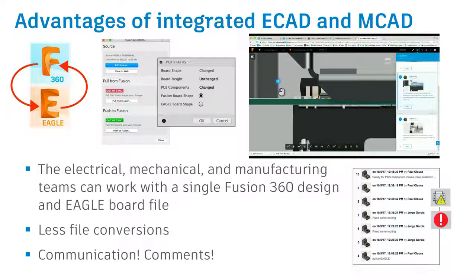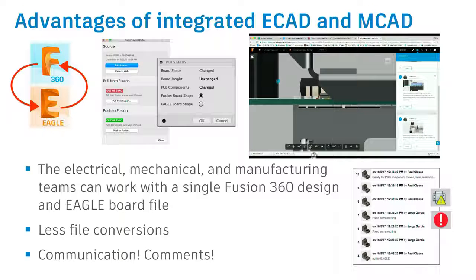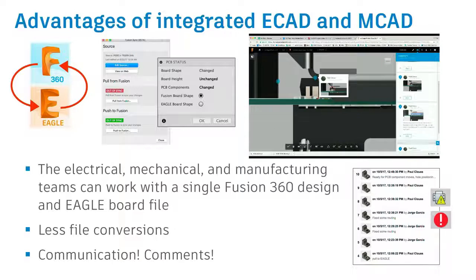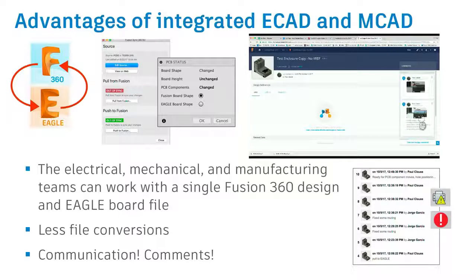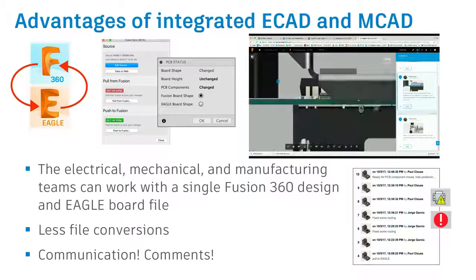So when it comes to the libraries, we have a system now called Managed Libraries, and we're giving the manufacturers of those components an account. Now they have an account, and I can see those accounts from within Eagle. Before, you would have to download libraries. You would have to navigate to the manufacturer and hope they had it in Eagle format, and then you would download that library, and hopefully you could convert it. If not, you would just have to recreate it.